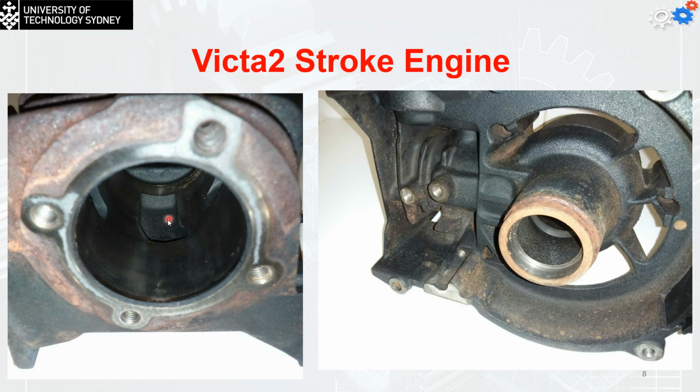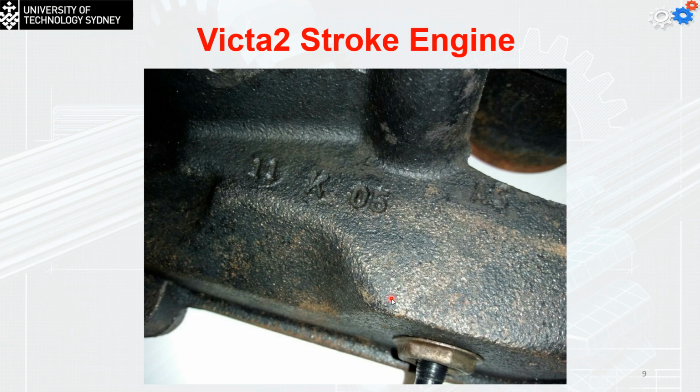This image can also show you some of the details we have inside, which you should keep in mind before you do the casting operation. I just had this photo to show you the shape or the surface roughness we have for this part. By looking at this surface, you'll say that this part has been made by the sand casting operation.